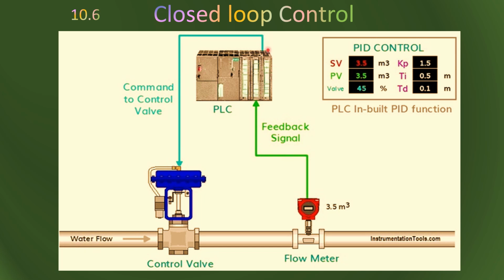Then, as I explained on the previous slide, we convert the digital signal to analog, and then it is fed to some type of control element or actuator which controls the flow. Like over here, the water flow we have to control. So if the control valve is opening more, the flow of the water will be higher, and whenever it is closed, the flow of the water will stop, and in between, suppose if it is 50% open, the flow rate will be 50%.